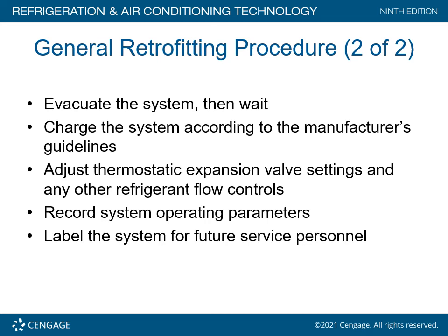Word of caution here. Some of the so-called R22 blends that are out there, you will see reductions in heat transfer capacity in the evaporator coil. R22 has certain characteristics. R407C, as an example, has certain characteristics. New 22 has certain characteristics. Please be aware of all the ramifications in order to achieve a 40-degree coil on an air conditioning application.